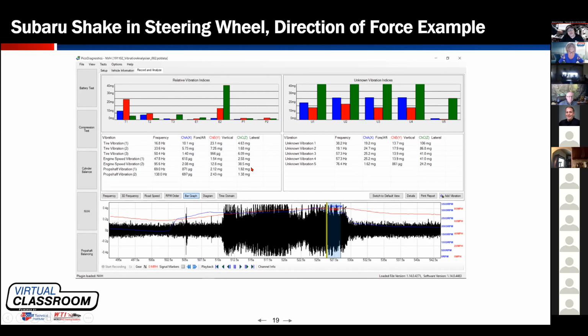The thing is, as we look at other unknown rotating components, not the standard tires, engines, prop shafts or drive lines rotating, this car produced some pretty wicked vibrations. Think about this. Wouldn't it make sense if I knew how many times per second a shake happened?